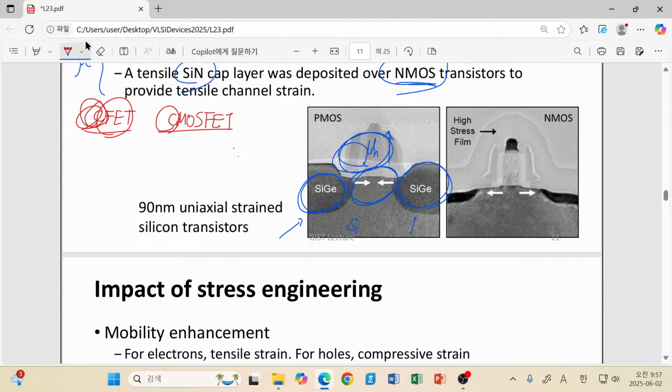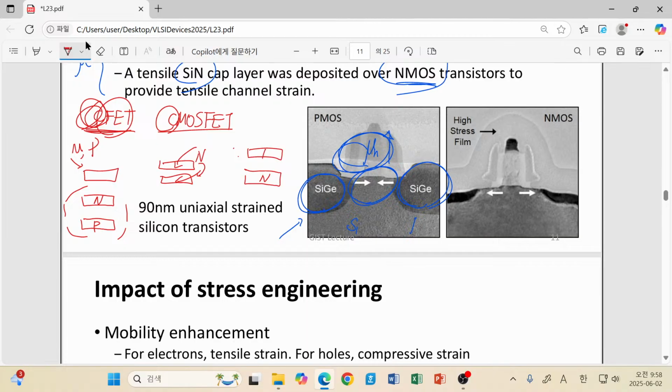They say that instead of making our NMOSFET and PMOSFET side by side in the top view, they just build one device which has NMOSFET and at the same time PMOSFET. Simply speaking, NMOSFET is just placed over PMOSFET. That is called CFET. In this case, we can have two different options. One option is to place our PFET on the bottom and our NFET on top. The other way around is to place our NFET on the bottom and PMOSFET on top of NMOSFET.